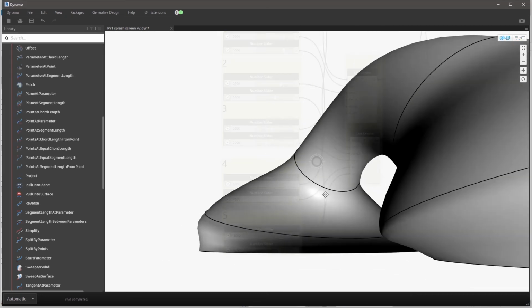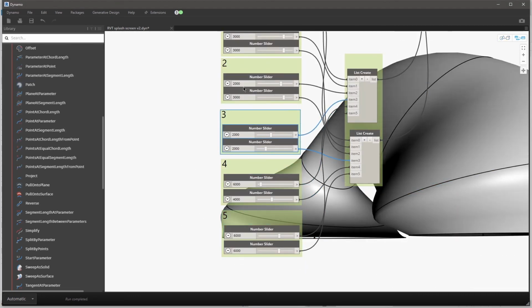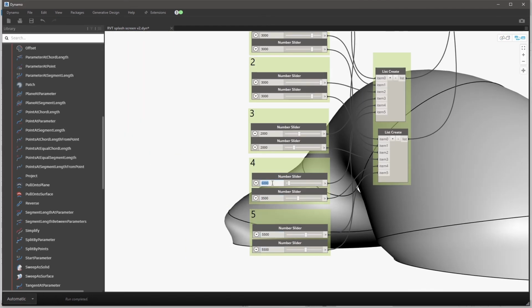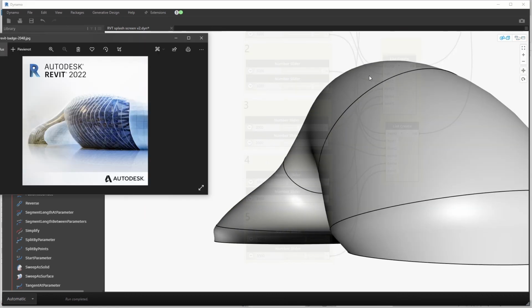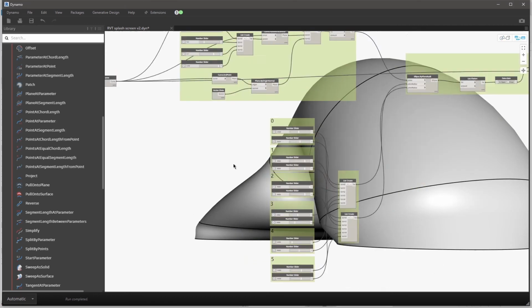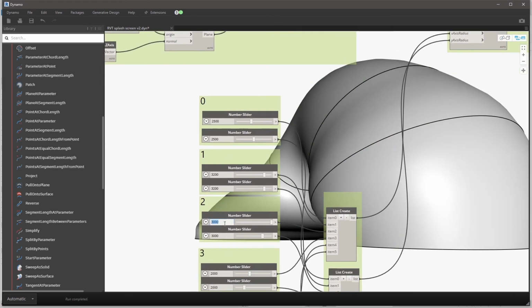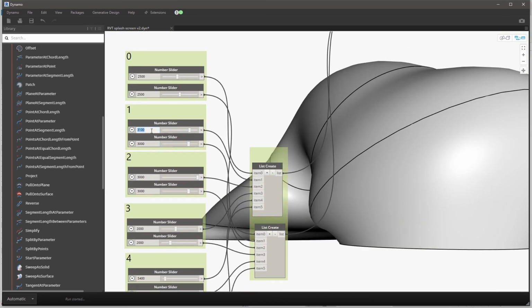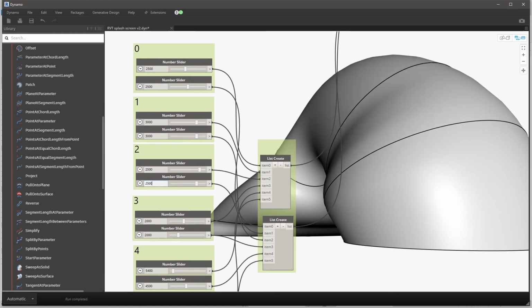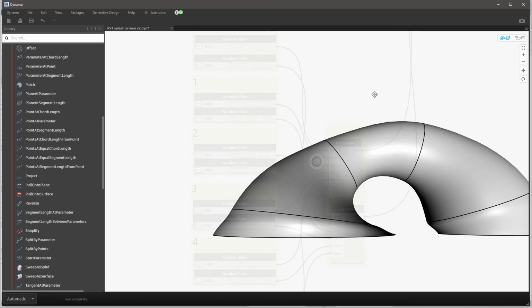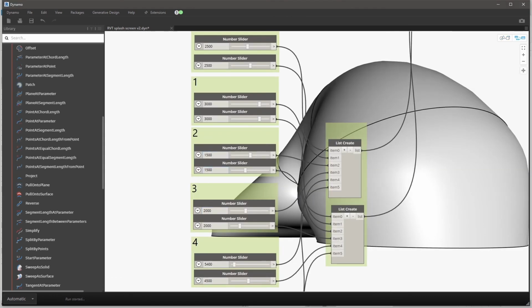I just look at the splash screen image, so I just try to get the right camera angle from where the image was taken, and in that way it's easier to guess the shape of the whole structure. So that's what I do here. I just look at the image, try to get the camera angle and change the radiuses of those 6 ellipses. And also I can change the position of those ellipses on the lead curve, and that dramatically changes the shape of the surface. And here you can see that I just slide those ellipses back and forth, trying to guess the right shape.